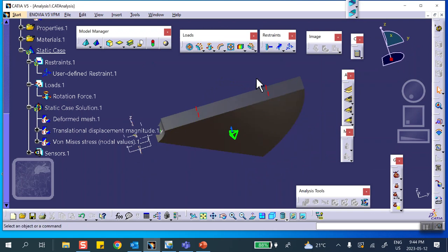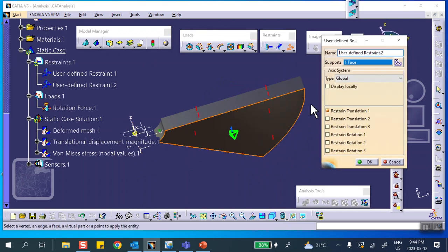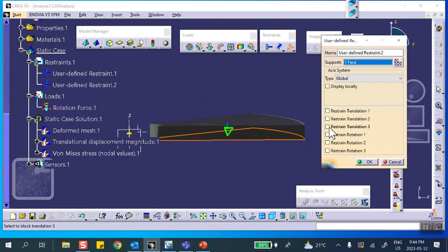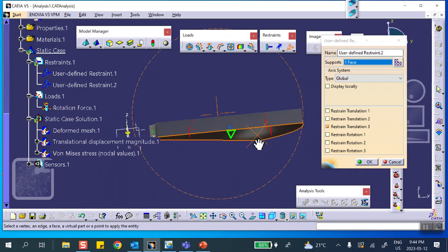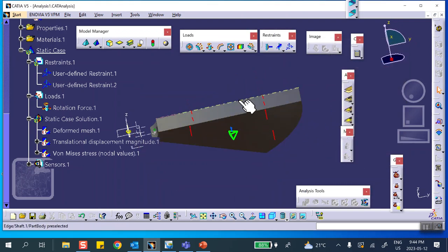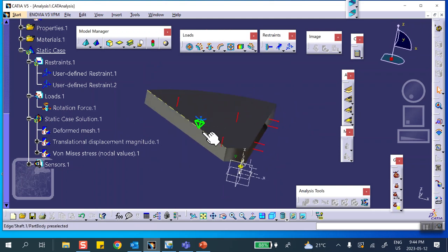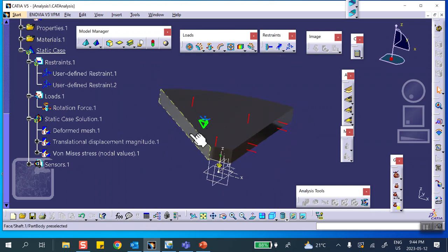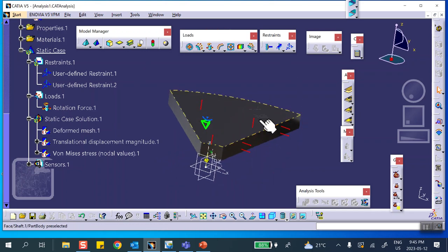On the bottom face, nothing moves perpendicular to it. Perpendicular to it is direction 3, direction Z. See that? Nothing moves perpendicular to it on that face. My problem is going to be on this face, because on purpose I took a 45-degree sector, so the normal to this face is neither X nor Y nor Z. In fact, it's at 45 degrees to X and Z. So here's what you're going to do.